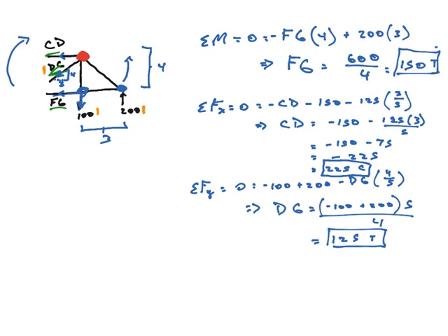For the reactions, or even when we do method of joints, usually you could use your logic to deduce which direction we think these forces should be in. Here, don't worry about it. Just think everything's in tension. Do the math. If you get a negative answer, you make it compression instead. But this is the method of sections.